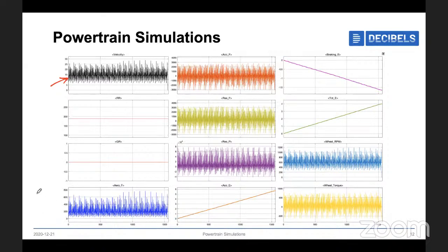So at higher speeds, this is our formula, half rho Cd A v square. So the v square term is there, right? Your velocity will be drastically increasing, and you'll be getting more resistive force here. Okay, and this is the acceleration force, and this is the total resistive force at each and every second of time. So from this resistive force we can calculate the RPMs and torques.